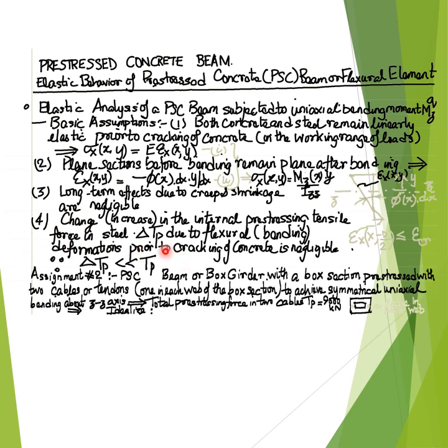Hence, by virtue of this assumption number 4, or the mathematical representation of assumption number 4, the internal tensile pre-stressing force in the concrete as well as the steel in case of the pre-stressed concrete beam can be assumed to be more or less constant prior to the cracking of concrete, even when the pre-stressed concrete beam undergoes flexural or bending deformations.